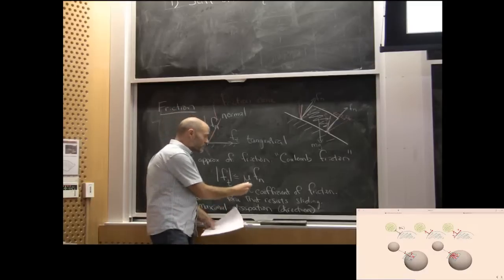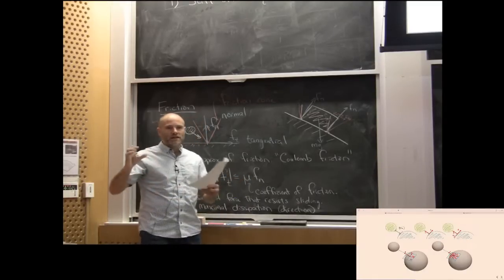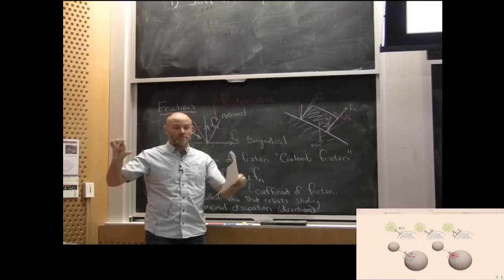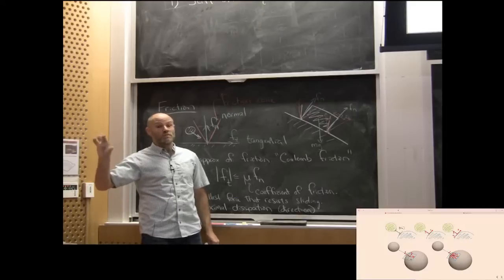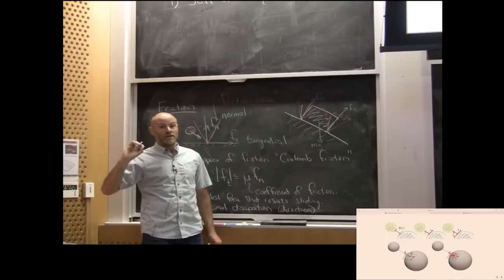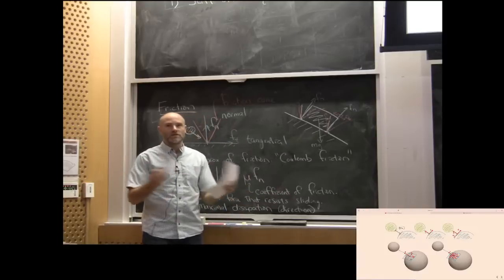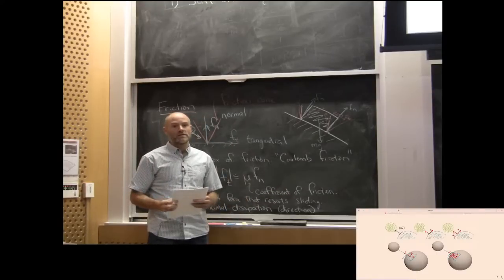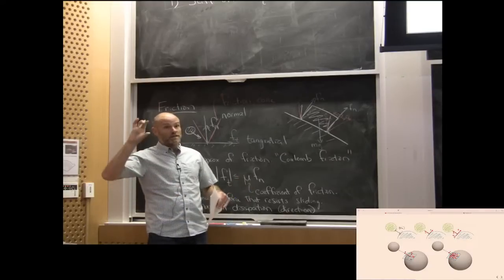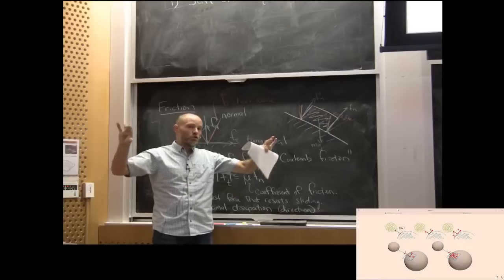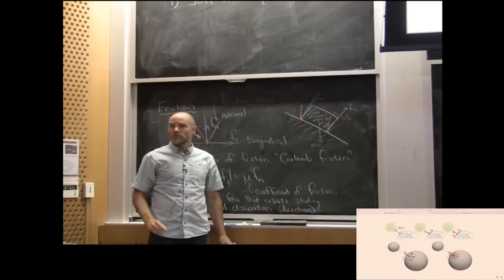Now, the interesting thing is that the coefficient of friction is really a property of the interaction between the two types of materials. So you can't say, this mustard bottle has coefficient of friction 3. It's when the mustard pairs with the steel table that it has a certain coefficient. It's in contact pairs, right? So it's a little annoying to specify, and people typically specify individual numbers for individual ones and come up with a hacky way to combine them in the simulator.